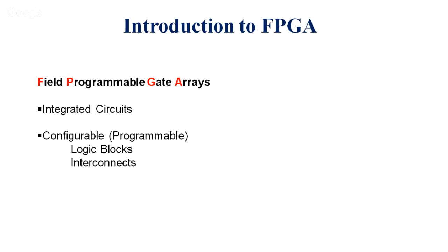From a research point of view, implementing our research or hardware on FPGA is much better than any other microprocessor or microcontroller. The most important beauty of FPGA is that it works on a parallel, concurrent basis. Here we flow data from input to output. In a microprocessor or microcontroller, we first write instructions or our program and store it in memory, then fetch these instructions one by one and execute. So they work on a sequential basis.